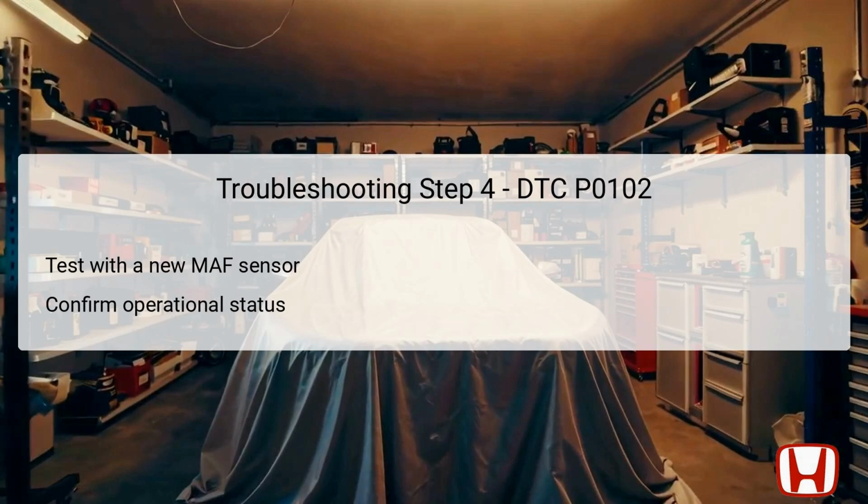Observing voltage output with the new MAF sensor should yield values above the malfunction threshold if the sensor was at fault. After the installation, ensure that all connections are secured and the vehicle is started to monitor for the check engine light. If the light remains off and engine performance improves, it confirms that the new sensor resolved the issue. This step is essential for confirming the health and reliability of the MAF sensor's function within the overall system.